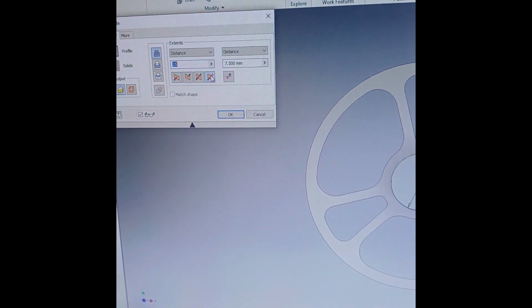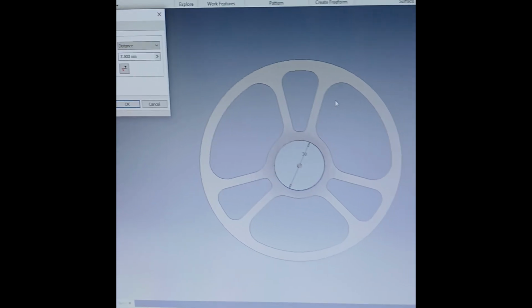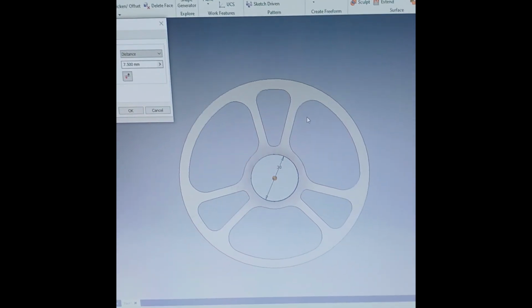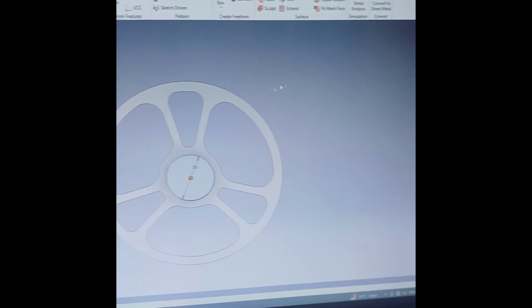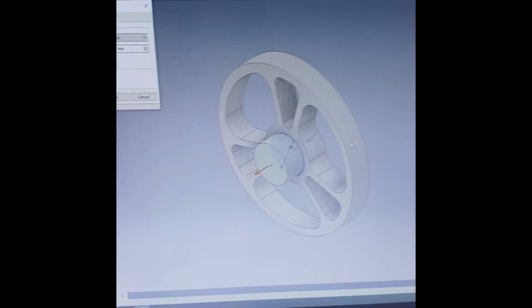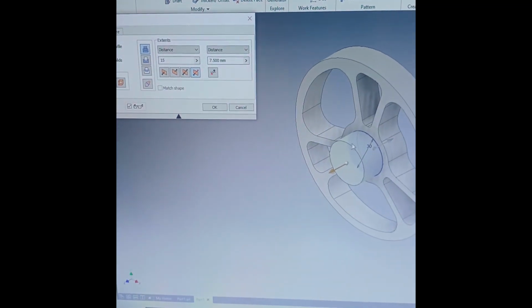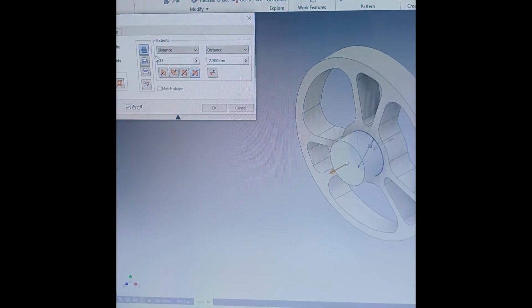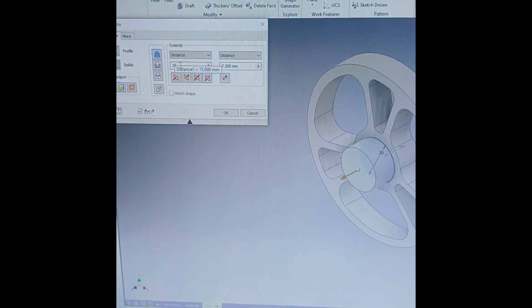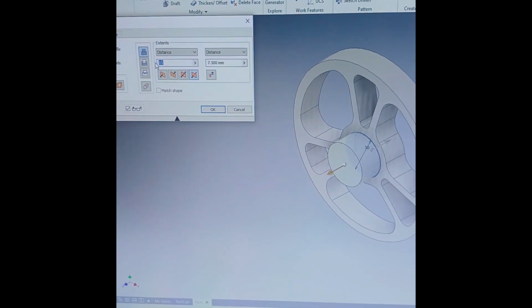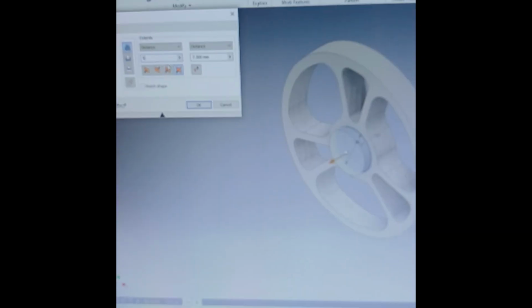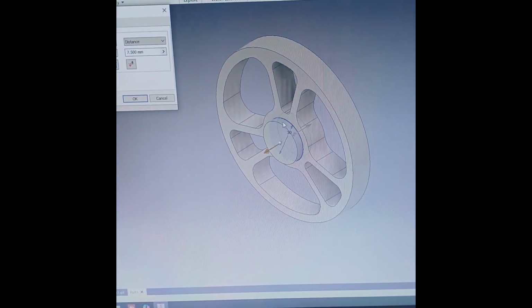Click on asymmetric extrude. Now I'll rotate the profile to explain. Okay. So you can just click on this edge to rotate. So you can see now. So it is taking 15 mm. This is the first dimension. So I have to take here 5 mm. Okay. So this will be the 5 mm extrude over here.